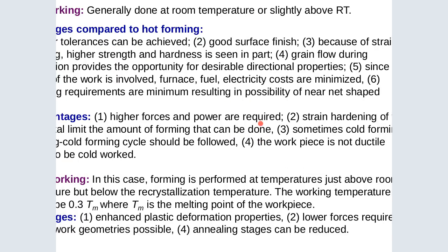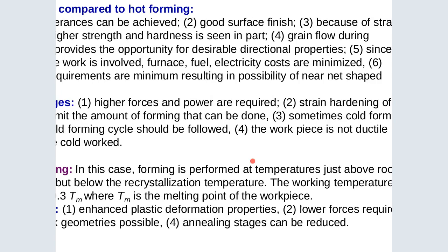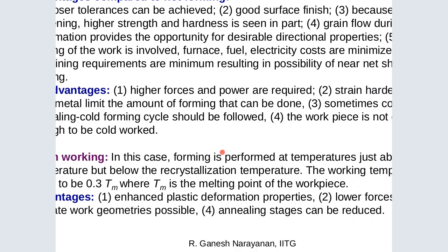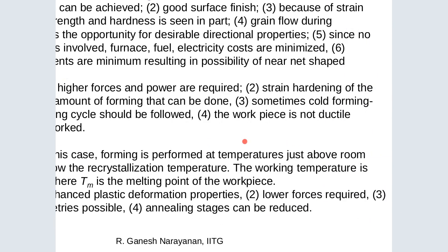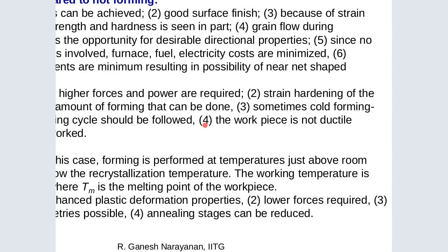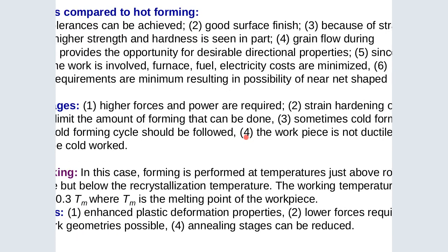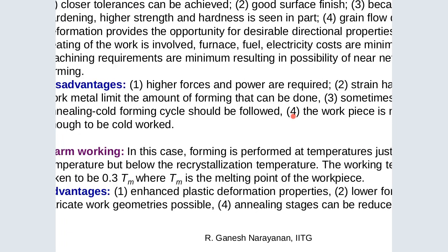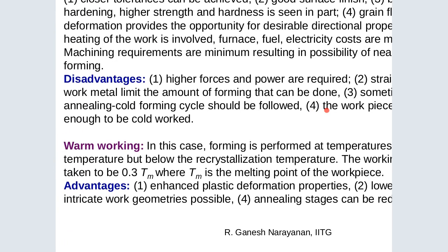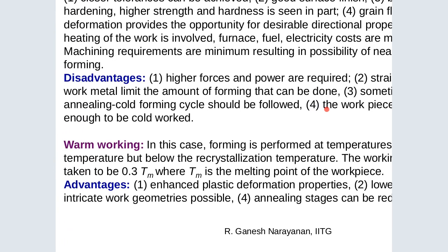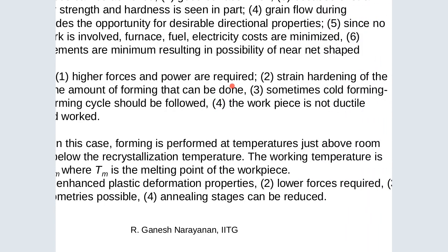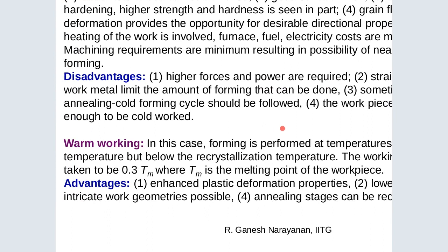And again, number 5, since no heat is involved in the work, the furnace, fuel and electricity costs are minimized because it is a cold working process, so it does not need any heat. Number 6, the machining requirements are minimum, resulting in the possibility of near net shape forming.